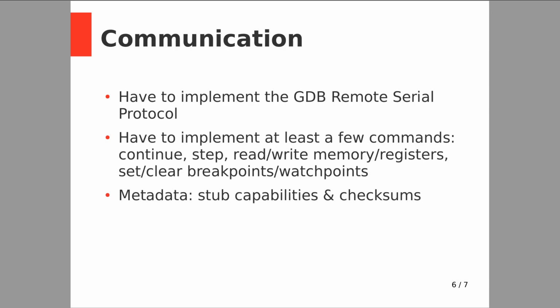For communication, we have to implement the GDB Remote Serial Protocol, which is a standard set of packets and commands and data transfer designed by GDB to communicate between stubs and the server. Through that, we'll have to implement a few commands like continue running the program, step forward one instruction, read and write memory and registers, set and clear breakpoints, and set and clear watch points.